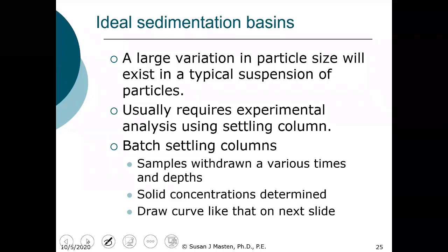In sedimentation, what we really want is the percent removal. So we're looking at removing particulates in the sediment, in the basin where we have quiescent flow. Unfortunately, wastewaters don't have a single size particle. They have a large variation in particle size, and we need to be able to describe or predict the removals of that suspension of particles.